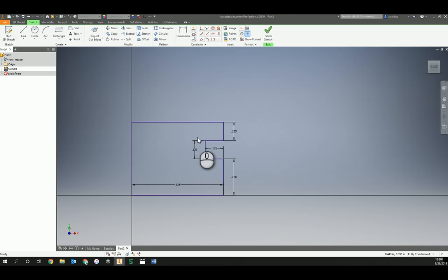But this isn't the image that we saw earlier. What we had was these square edges were rounded. Now the tool we're going to use for that is called fillet. So I'm going to select the fillet tool here, click fillet, but I don't want it to be 0.125. That's going to be too big because these are 0.125. That's going to be the entire half of this. So I want half of 0.125. Well, 0.125 is the mathematical expression of 1/8. Well, what's half of 1/8? 1/16 is half of 1/8.